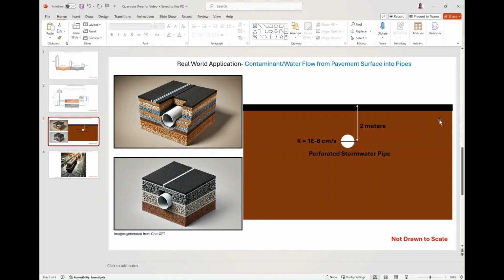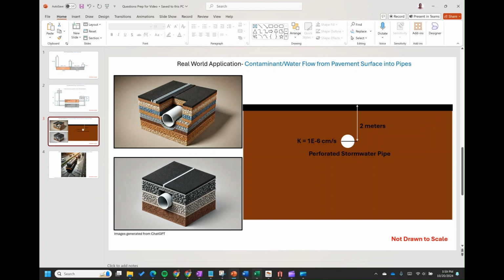Or we can increase it to 300 by 50, and you can check the percentage difference before you go ahead and say it is okay for your domain. Let me say that again. After trying out the first domain, you can do a bigger domain. For example, I'll be trying out 200 by 50. You can then do 300 by 50 and compare the output to know if there's much difference between the first domain and the second domain. Usually a percentage difference of about 5 to 10% is okay for you to say the domain you are using is fine. So we proceed to FEHT now.